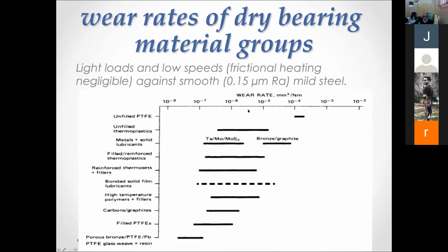So today you will just try your numericals from the book or any application for design of plain surface bearing. You can take any load, any speed, and any journal diameter, and then you see which type of material is suitable, which will give that PV property. Then you will also find the clearances, and then we will have next time discussions on wear.